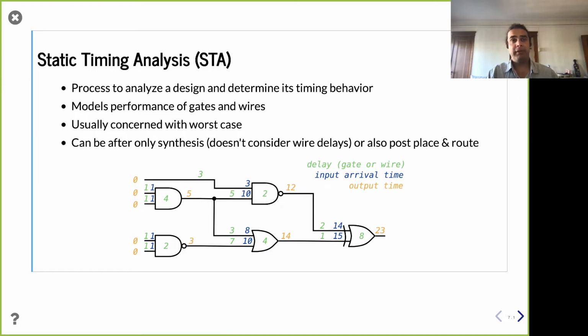You can imagine perhaps a more detailed dynamic analysis might say, oh, wait, if I know this is a 1 coming in here and a 0 coming here, I can do various analyses, or perhaps I notice that our input is later, maybe we'll never reach a certain value and thus I can't change this. These are things we don't need to worry about for now. But with STA, we're being very conservative, right? It's looking at the gates just generally and seeing what we can do.